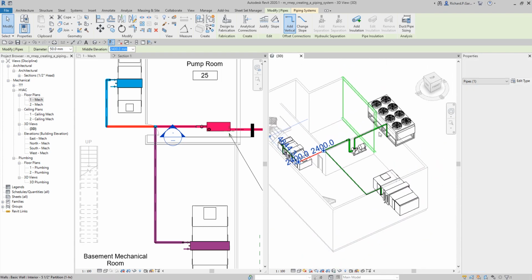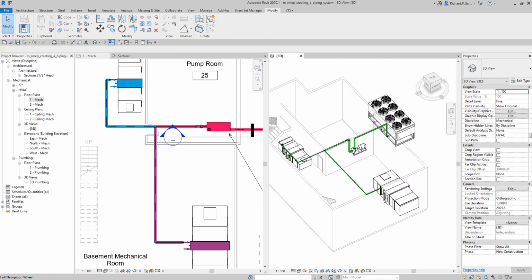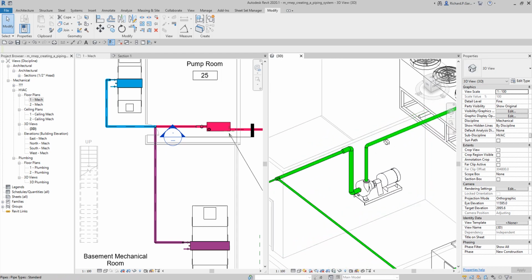Okay, and another thing that you can do here is you can also do piping sizing, right? Sizing your pipe. So what is this pipe sizing? So you have that also in your ducting, right? So the methods of pipe sizing here, it uses certain piping element properties in sizing the pipe. So the material of the pipe determines the roughness, and pipe fittings used in the pipe type family determine the algorithm to be used in the sizing of the pipe.